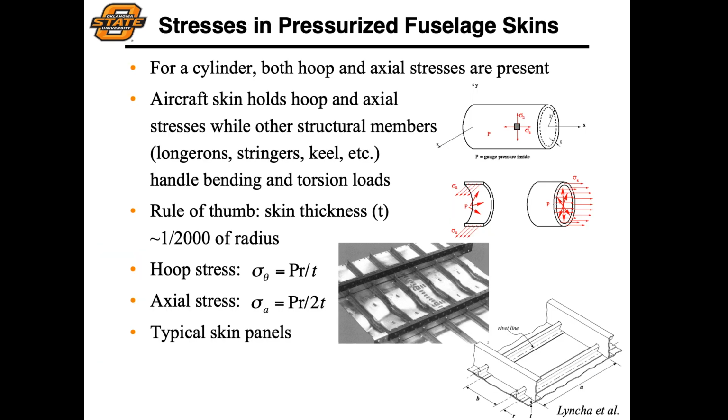Now, as I mentioned earlier, we're going to do a pressure vessel analysis for the structural design of our pressurized aircraft members. From this, we assume a cylindrical aircraft design, for a structure that has a high aspect ratio. That's going to be the most optimum and lowest weight solution for us.